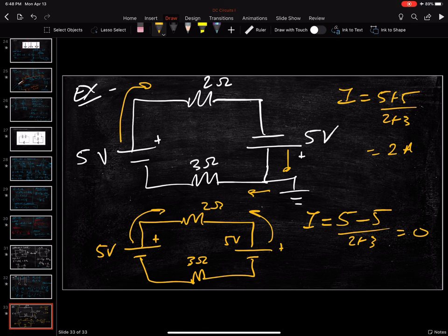Remember, I talked about how you got to bump up in voltage when you're moving in the same direction as the current. The current's going this way. Here, you're fighting that. Here, this pushes back. So, because this second battery is pushing back, it's costing energy. It's draining energy away from those charges. And so you lose voltage when you go in that direction. Okay? That's the idea. What if it was 6 volts and 5 volts? Well, it'd be 6 minus 5. You'd have 1. And so the current would just kind of trickle. Okay? That's the idea.